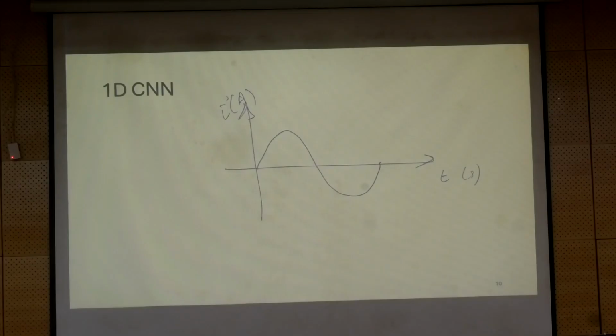So my data itself will not be like this, but instead, depending upon the sampling rate, if I have 60 samples per second, or 50 samples per wave, I will have so many points. So I will start with 0, then here, then here, then here, like this, right? So this will be the samples that I will be working with. Each one is a sample, and this is the sample that will be stored in my data set. So my data set is actually a sampled data set, right?